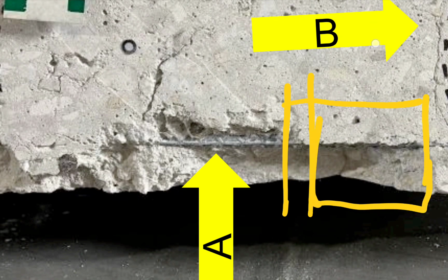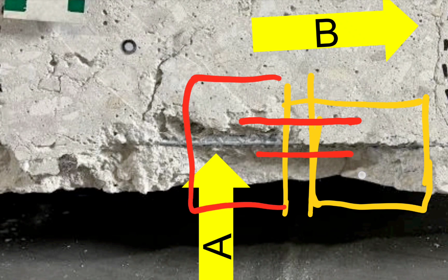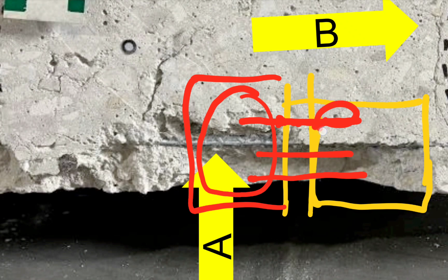The internal flooring has steel in it, and some of that steel's development length is out here. Here's a cantilever here. I'm worried it's out here. If you just go at it like a jackass and start jackhammering on top of some of the steel, it could vibrate through the wall and start fracturing the anchor points inside the structure. Definitely out here, but anchor points.